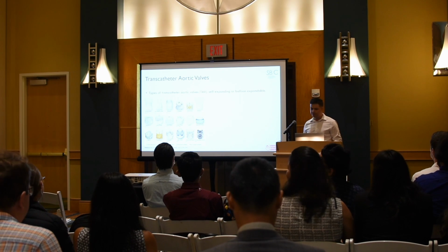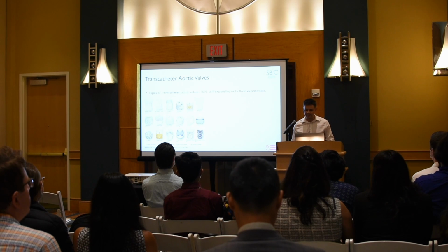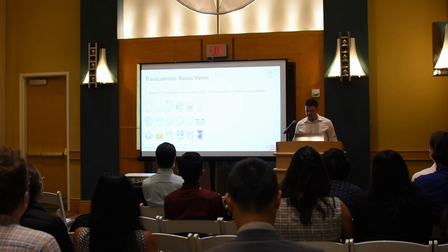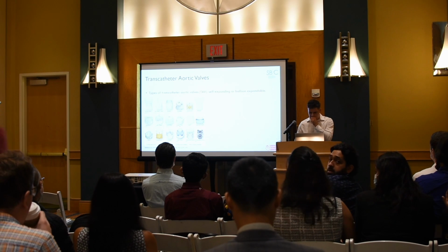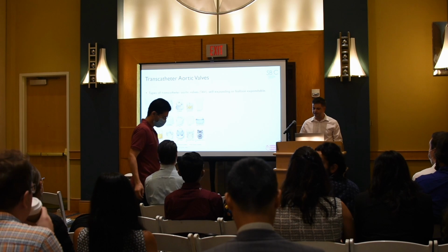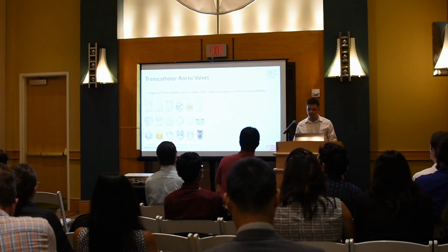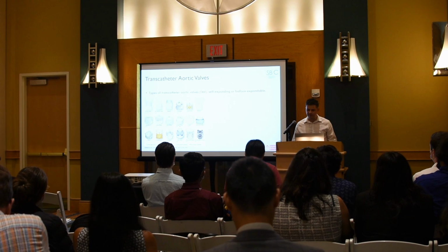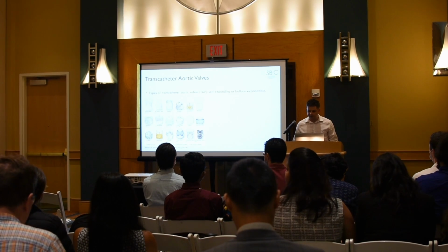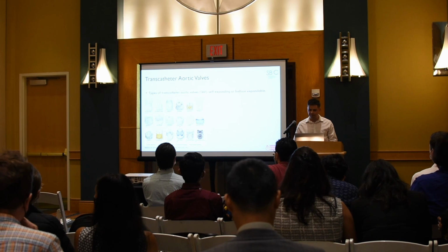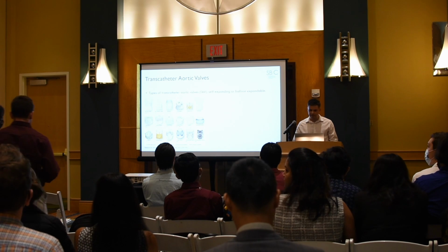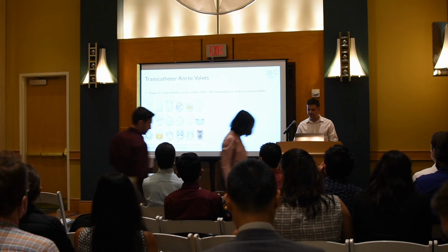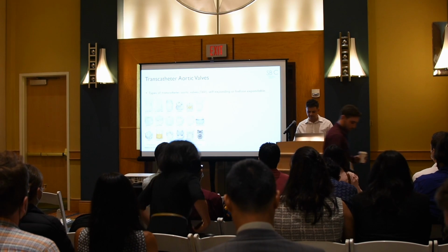During the last two decades, there have been lots of improvements in transcatheter aortic valve designs and materials to optimize valve performance and maximize the benefits. Such as replacing stent metals from stainless steel to cobalt chromium to ensure stronger and more efficient anchoring. Skirts were also added to limit regurgitation, and the valve profiles were altered to allow minimal interference with the downstream flow. As you can see, there are lots of different types of transcatheter aortic valves in this image.